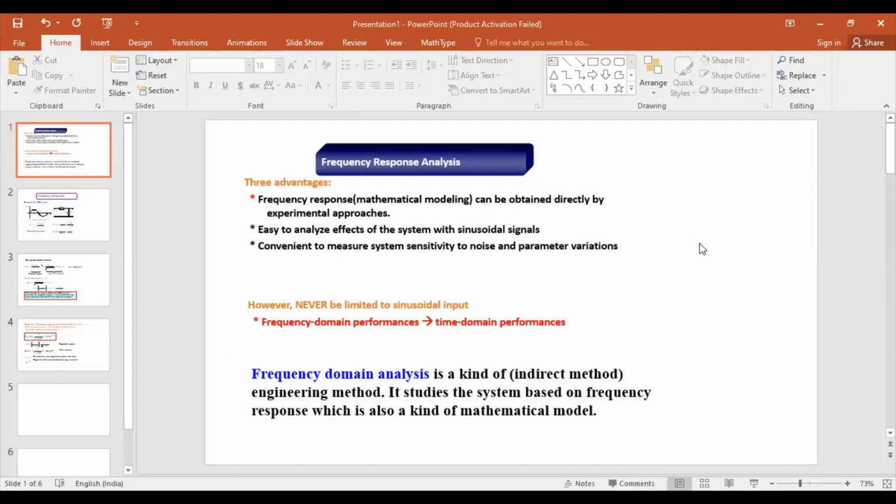So, with these three key points, let us come to one simplest example of frequency domain analysis, which we have already done in your term physics. That is nothing but the RLC circuit. You connected an RLC circuit with some values of R, L and C. Then you switched on an input signal of the type sinusoid. Then you went on varying the input frequency, keeping the amplitude constant. At a particular point, you noticed that there was a maximum current flow in the circuit. That condition, when we encounter maximum flow in the circuit, we call resonance.